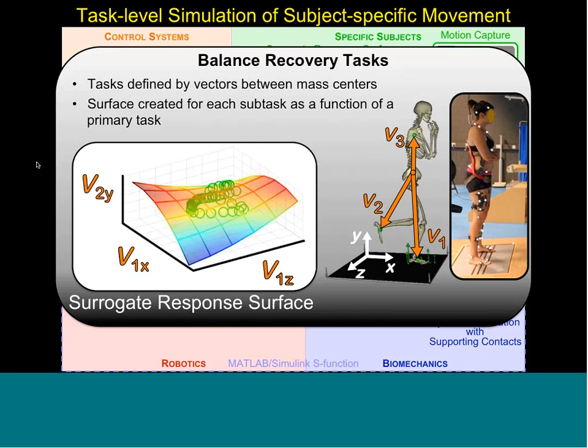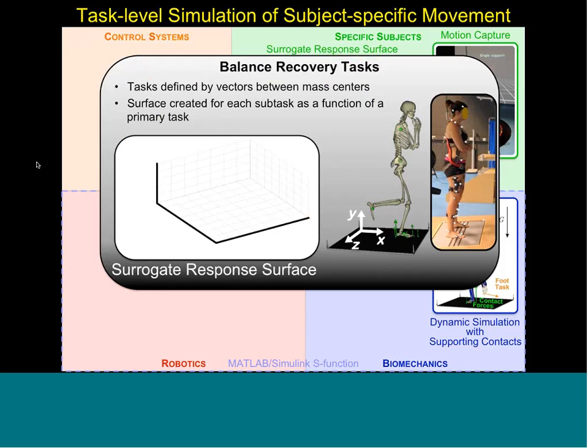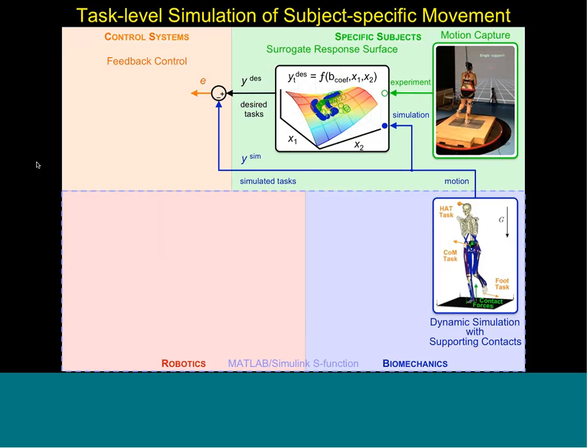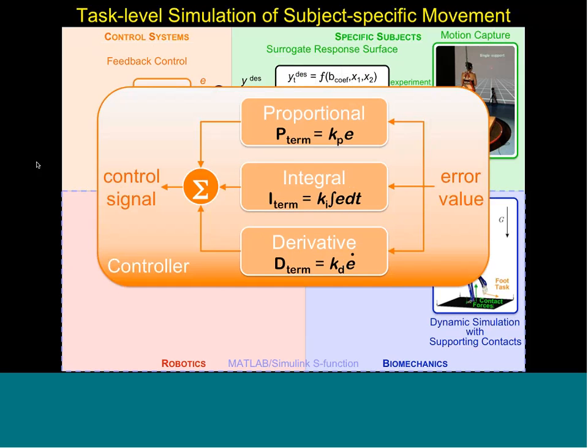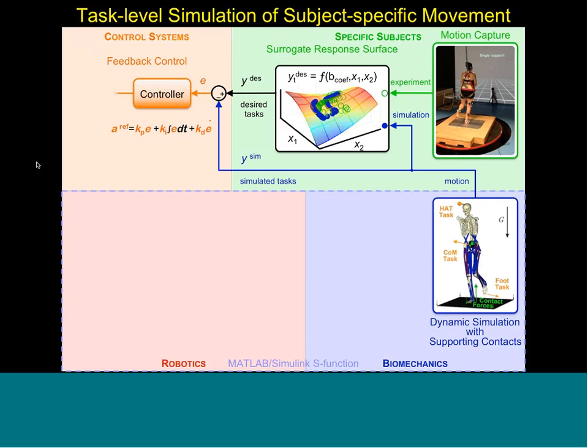Yeah, so the response surface, definitely what we've shown you here is the positions of that end effector for the swing limb. And then task 3 was the position of the center of mass of the torso. Those do get converted into task accelerations though at the dynamics level. So what we're trying to figure out is what are the joint torques to get that center of mass into a desired position. So if I had to put units on those axes, it would definitely be position units.